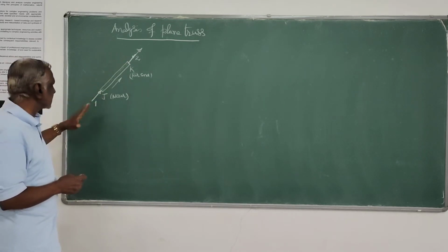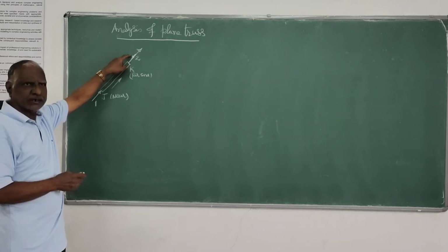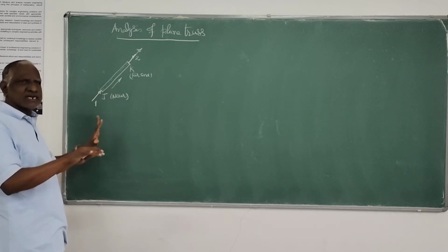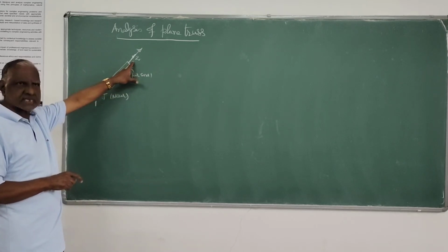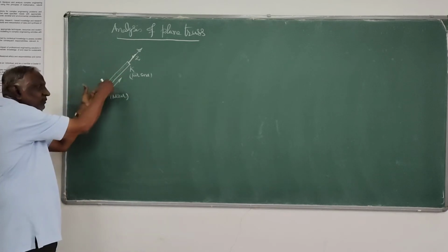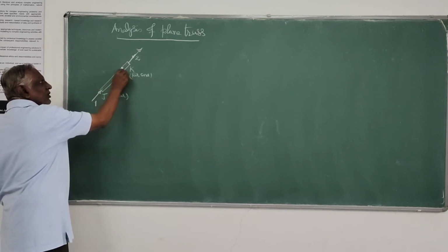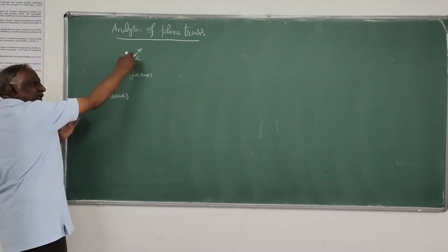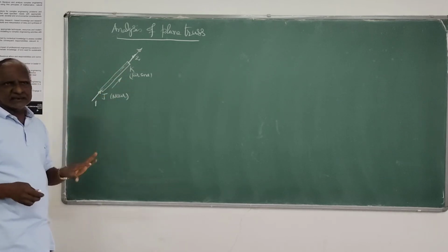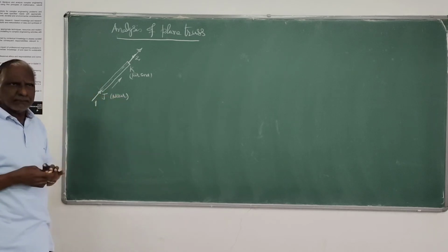Positive direction of displacement will be along this line, in this direction, whatever I have shown here. In the direction of 1, the positive direction of displacement as well as force. Here at this far end, this is the direction, the same direction. Then member force we can determine outwards. For equilibrium, it should be equal and opposite, here also equal and opposite. Then we can say whether it is in compression or tension. During the analysis we will see how to find out the actual member forces.